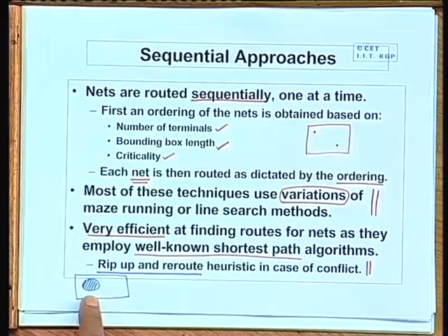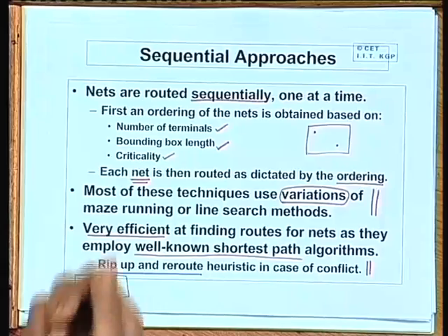You identify that region and you withdraw some of the already routed nets from that region, give them lower priority and again proceed. Maybe those nets will find some alternate paths of routing, but the nets which are trying to route currently, for them you are not finding any alternate path.